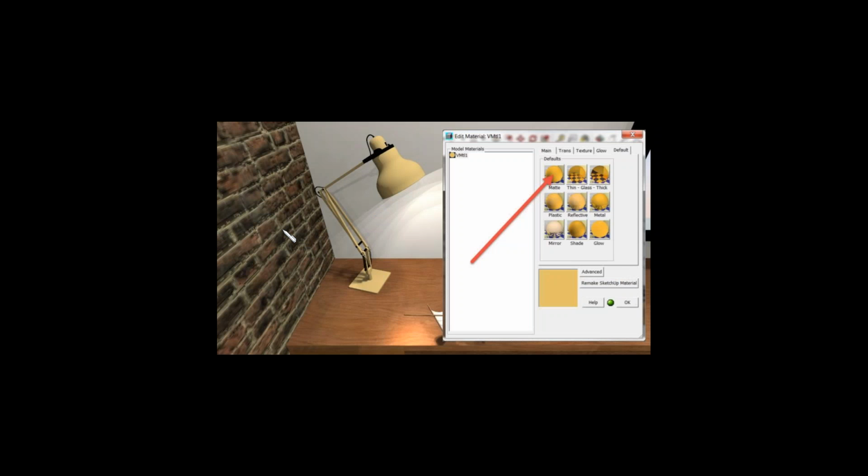Now first, let's review again the idea of the material finish presets that are available with IRender nXt. By default, if we haven't established a finish for a material, the materials are going to be rendered using a matte finish. That's what's being used right now with this lamp. And what that means is, you can see the intensity of the reflection and highlighting is set to 0. That's what the matte preset will do.